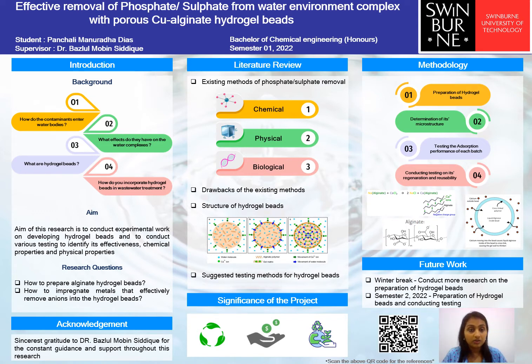Taking chemical into consideration, the most common practice is incorporating common chemical systems for salt sedimentation and coagulant precipitation. As an example, the use of lime or calcium hydroxide is very common. The most common physical methods are anion removal through the magnetic field method, where you use an activated magnetic field to isolate the anions, and electric coagulation, which uses an electrode to accumulate the anions. The biological methods include the use of certain identified or modified bacteria species just to remove the targeted anions.